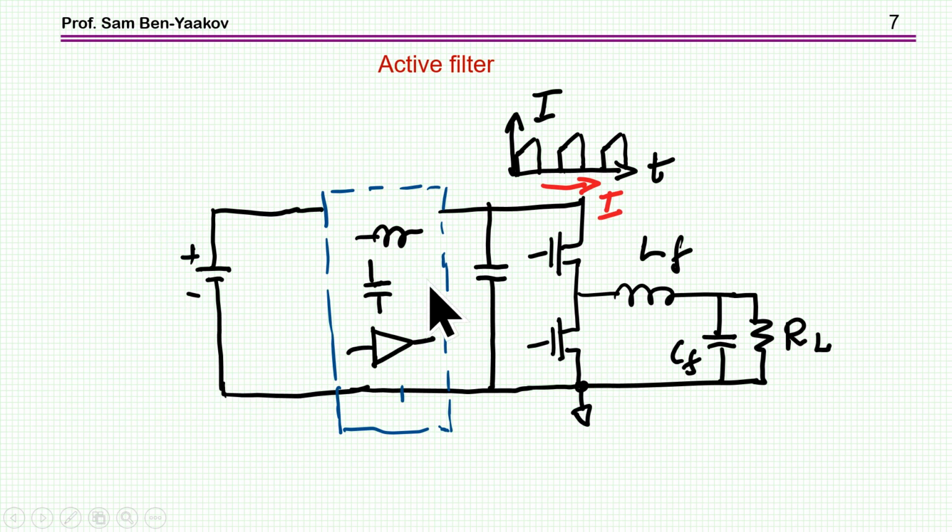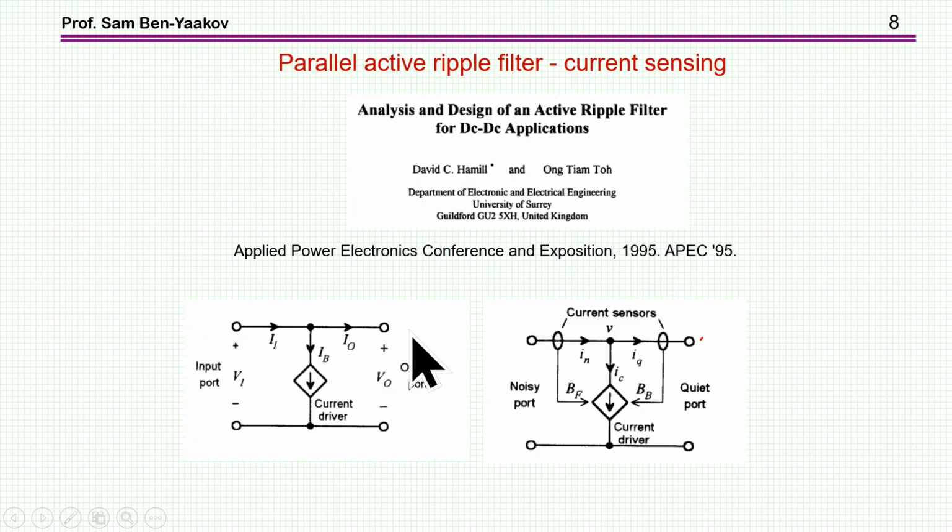There is an active approach in which you use an amplifier or another active device in order to emulate a circuit that supposedly has an advantage in that, say, it's smaller, more economical, rather than having a passive component, which might require a fairly large size inductor and high capacitance capacitors. So this is the idea of active filter.